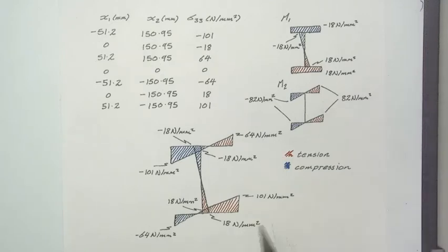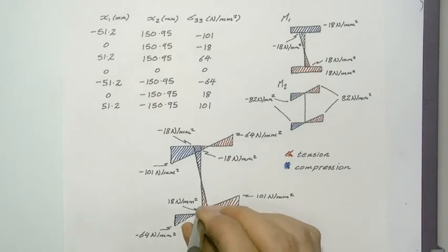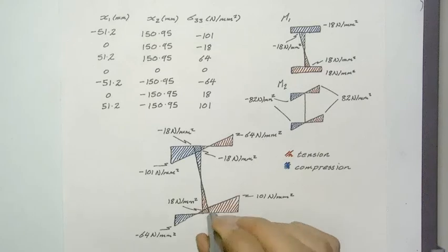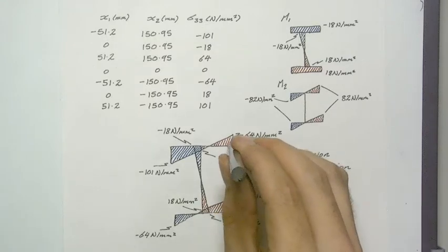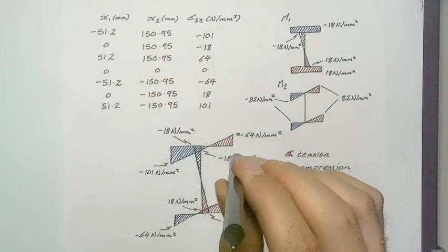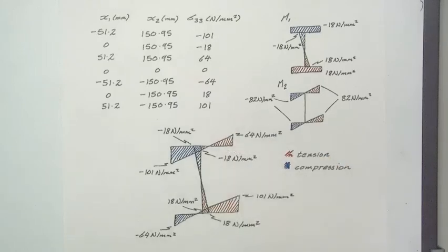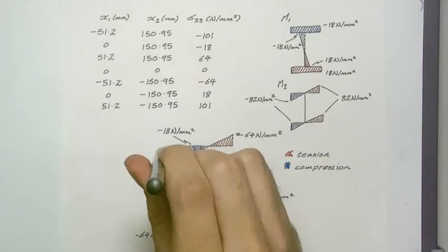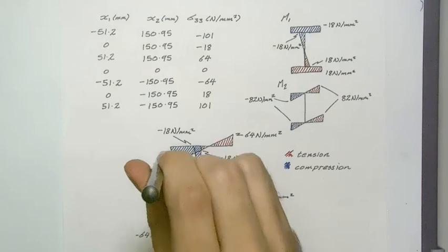An important point just to note for these diagrams is that they're obviously not giving an indication of the direction of stress. The stress in all of them is coming out of the page directly towards you. So when we have a tensile region, it's coming out of the page towards you like so. When we have a compressive region, on the other hand, it's as if it's going back into the page like so.